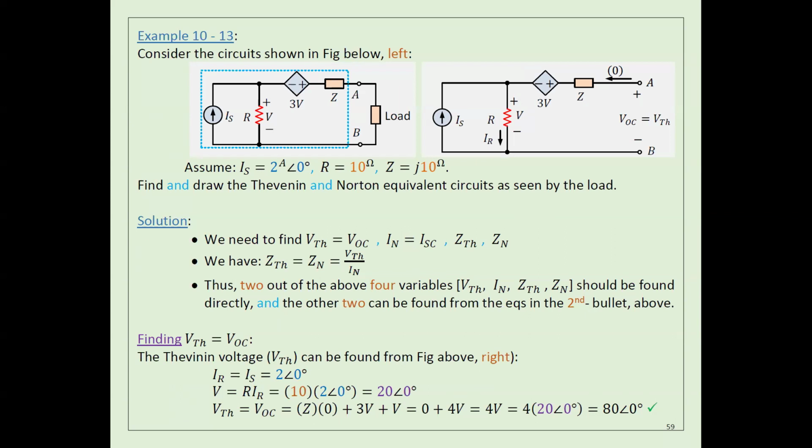But the 3 volts going from negative to positive, is that still a positive 3 volts, and you don't subtract the 3 volts? Yeah, so this is not 3 volt. This is 3 times V. Oh, okay. This is 3 times V, and this is V here. You got what I'm saying? This is not 3 volt. This is 3 times V, and V is 0.